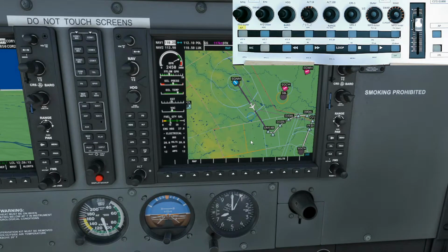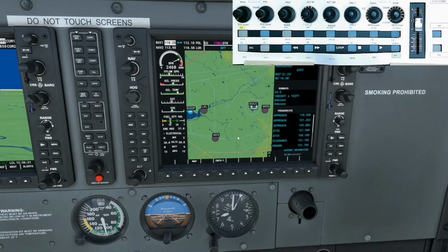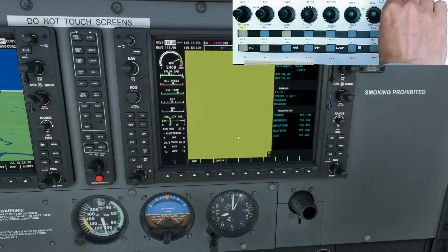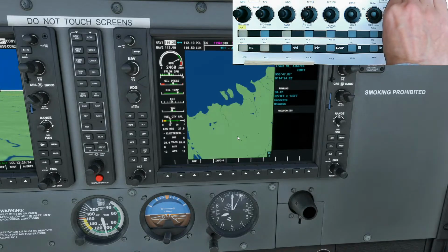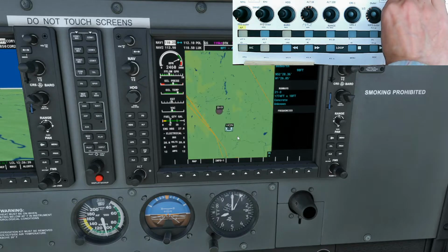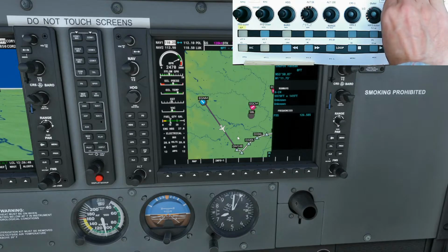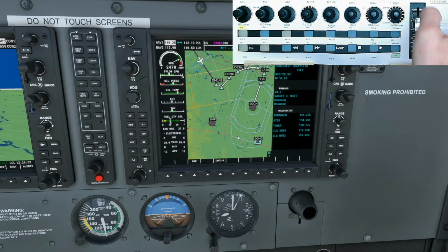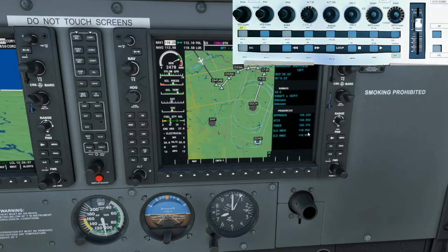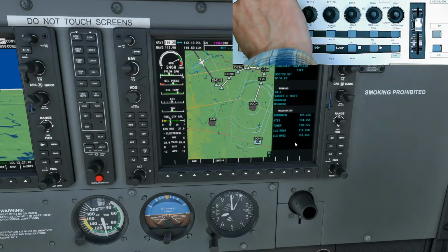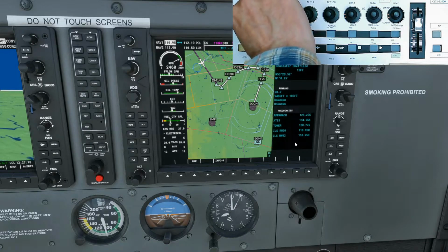And I want to have time to find the ILS frequency for that runway 20. So, airport information for EGCN Doncaster Sheffield, that's where we're going, that's okay. And my ILS runway frequency, well, both frequencies are the same, 110.95, so I'll need to put that into the nav up here. So back on layer A, 110.95, and make that active.